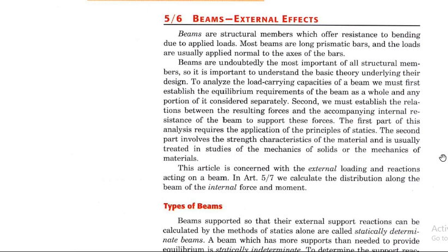Before going to the complete introduction, the first part of this lecture is that analysis requires the application of the principles of statics. Basically all the beams, all the external or internal parameters will follow statically determinate structures. If there are more forces or more supports than required, then the beam will be a statically indeterminate beam.